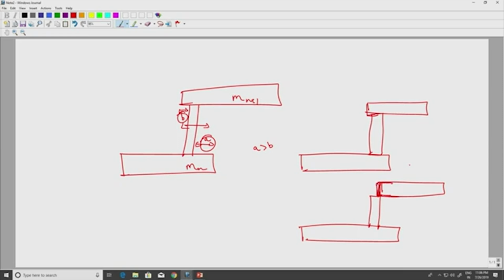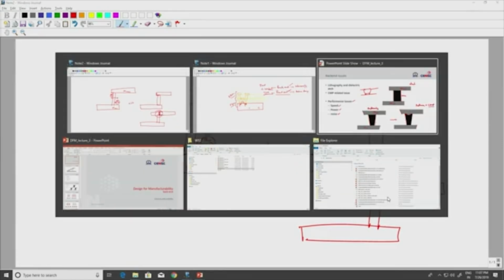It is just a matter of time before you have a very large current field here, and electromigration can happen that could result in failure. So you want to make sure that metal layer overlap is taken care of by applying the right amount of clearance so that you avoid alignment issues.